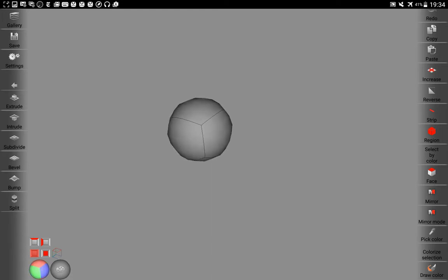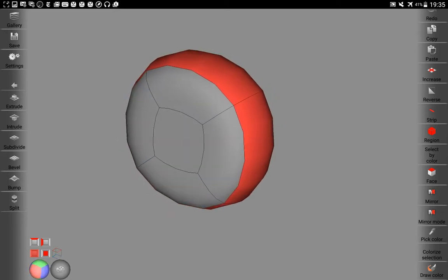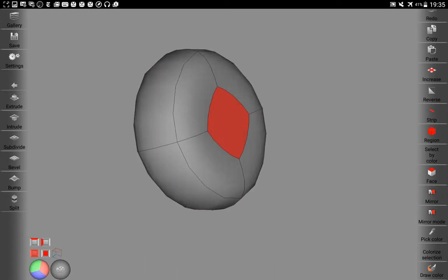There's some things to understand. For example, how to make a round form. That's always a very interesting question, and some people have already figured it out. You select just the surroundings with a strip command, so that it goes all around the object, and then we go to shape and use the extrude command, and we're getting this.